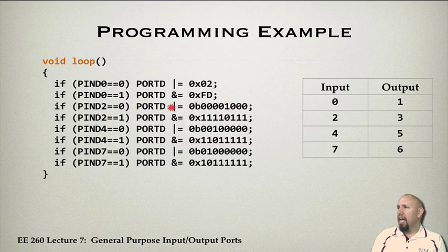And notice, actually these two commands are like the digital write. And so it depends on whether you're digitally writing 1 or 0. And actually, the digital write does a lot more than just these commands, but it's actually doing these two commands. So when you send a high or a low to digital write for a certain pin, it looks at whether it's a high or low, and it will do one or the other of these two things. So this is what's happening with pin 2 as the input and pin 3 as the output.